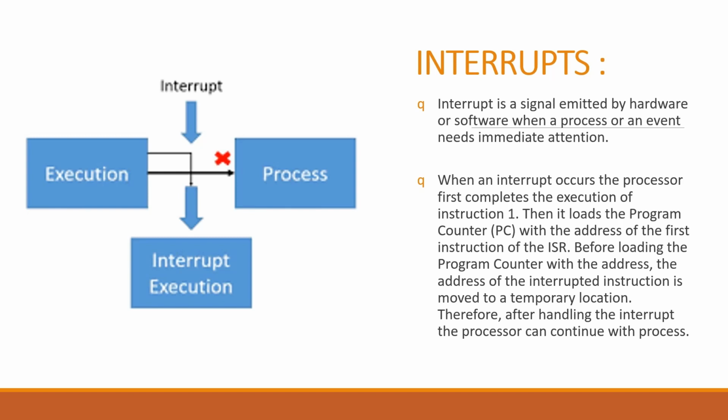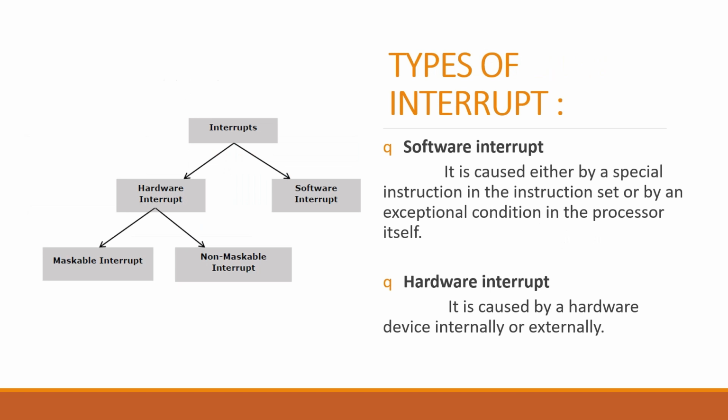Then we are moving on to interrupts. An interrupt is basically a thing which interrupts the normal process. The microcontroller works on a normal task given in the main function. When the interrupt occurs, the CPU is interrupted and redirected to the ISR function, the interrupt service routine. Then it starts executing the steps present inside the ISR function. After executing those steps, it returns back to the original process and starts executing the things given inside the main function.